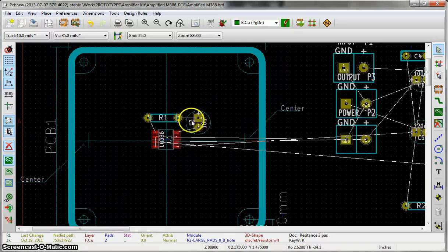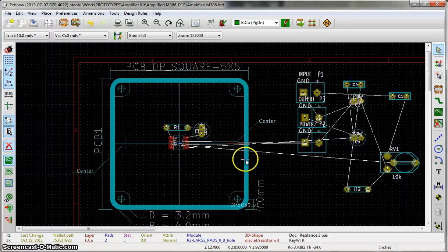And that's what I do for the components. When I'm then putting down the PCB tracks, I set the grid to 5, but I'll show you that in a second. So I'm going to spend a bit of time putting all these on, not put any PCB tracks between anything, but fit everything onto this board, and we'll see where we go from there. Just going to pause it now and I'll come back in a second.